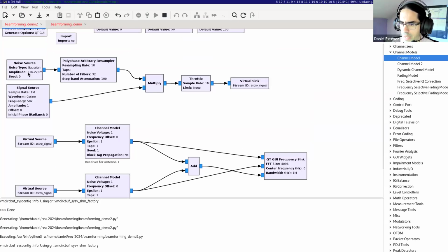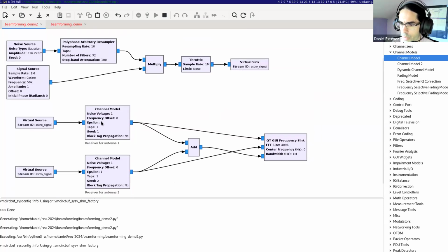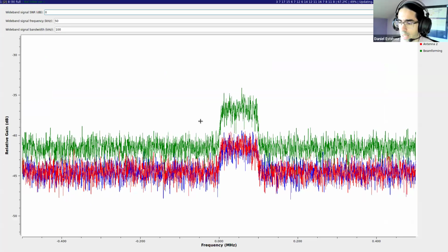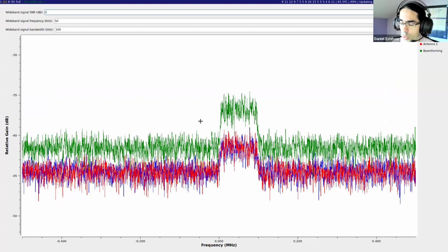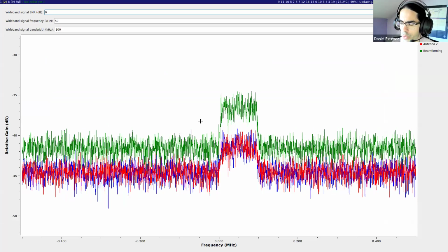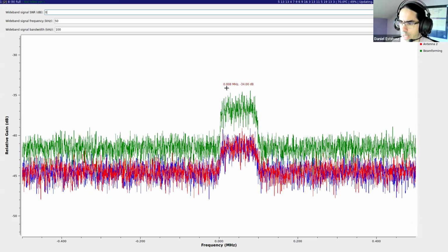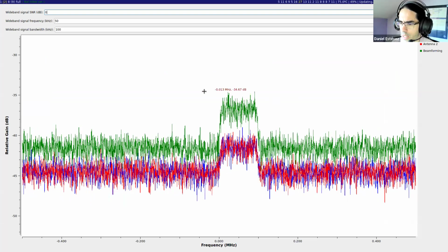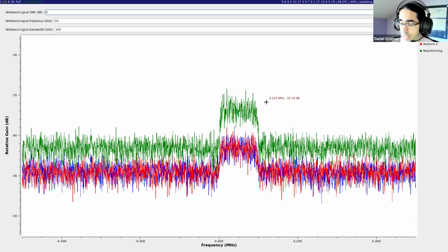We have basically the same signal, this astro signal, coming in through here, and it gets added. So the amplitude is going to be twice the amplitude here. Basically, I'm adding 2 copies of the same number. And increasing the amplitude by 2 is the same as increasing the power by 4, because power is amplitude squared. And if we express that in decibel units, that's an increase by 6 decibels.